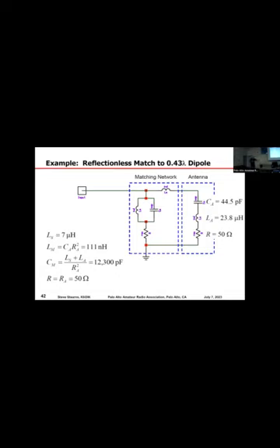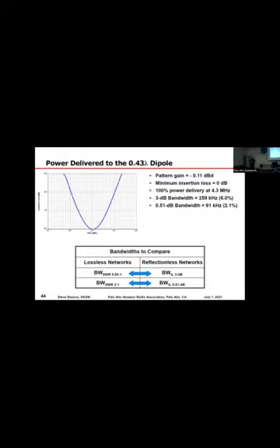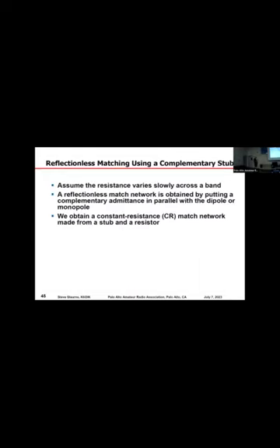And that's what we're seeing on the, if we now jump forward 3 slides, there we go. There you can see it's happening. What we're seeing is the insertion loss, 0 at the design frequency, and then it walks away from 0. But the SWR doesn't walk away from 1 to 1. All that's happening is the power that would have gone into the antenna is now going into that extra resistor. So this network makes the antenna appear to be 0Q.